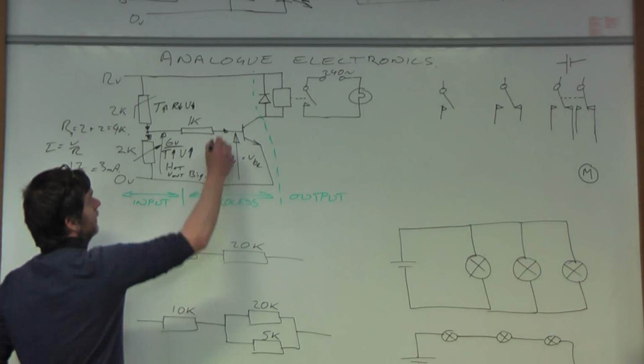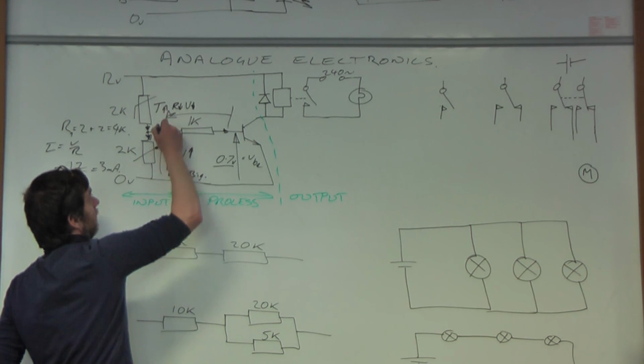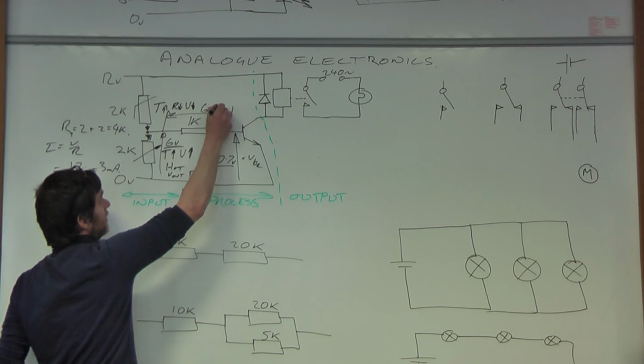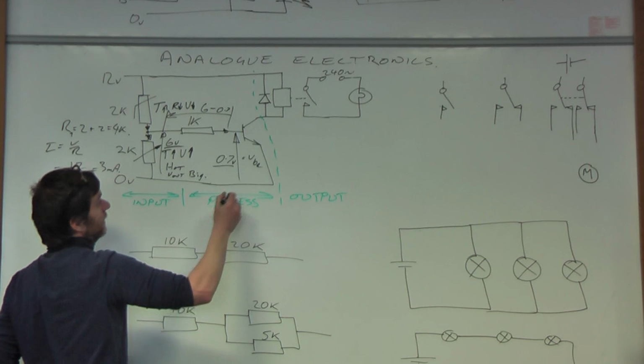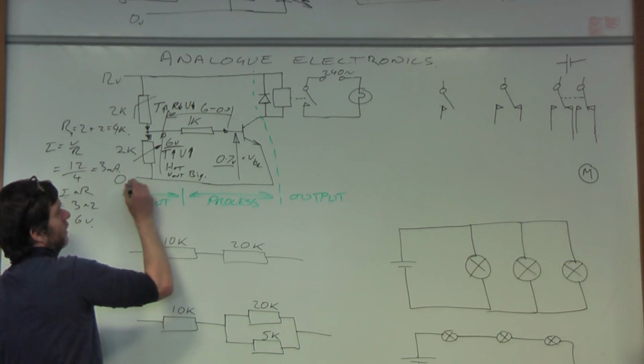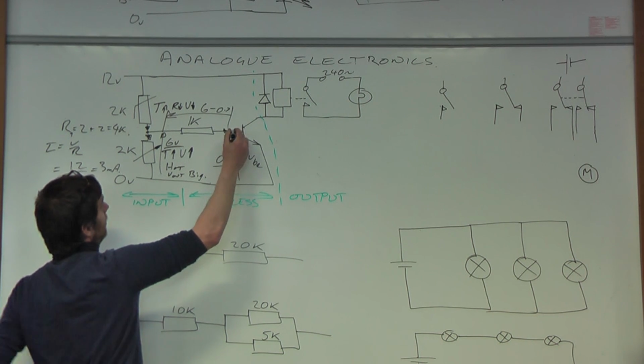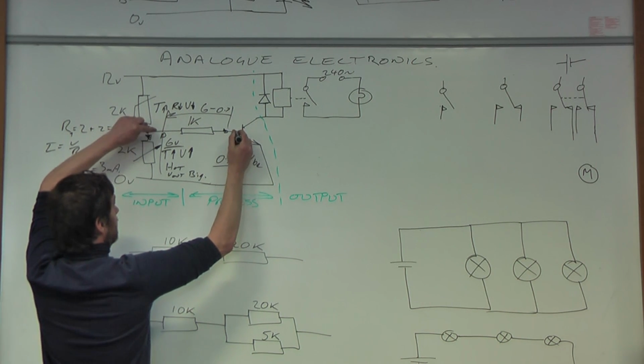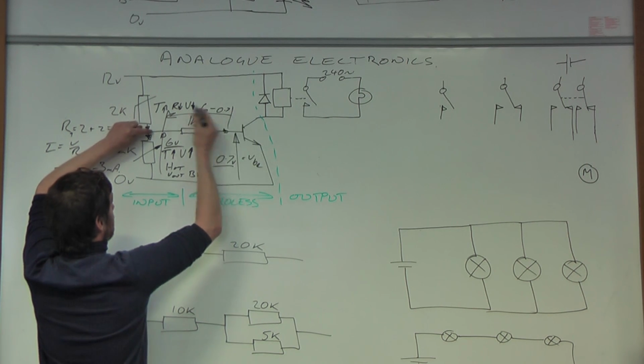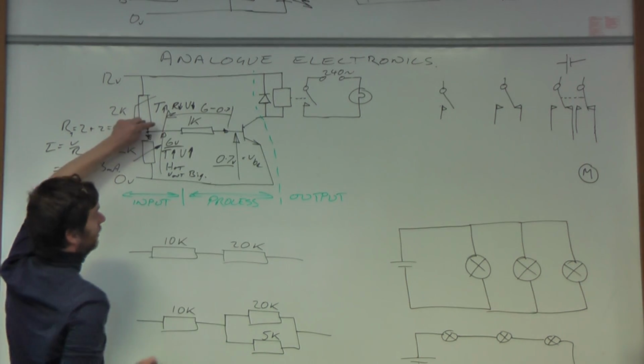That's 6 there. That voltage there must be 6 minus 0.7. If you imagine walking, you're at the bottom of a hill, you climb up 0.7 there, you can see this bit is 6 volts, so as you're looking across, you're seeing 5.3 up.